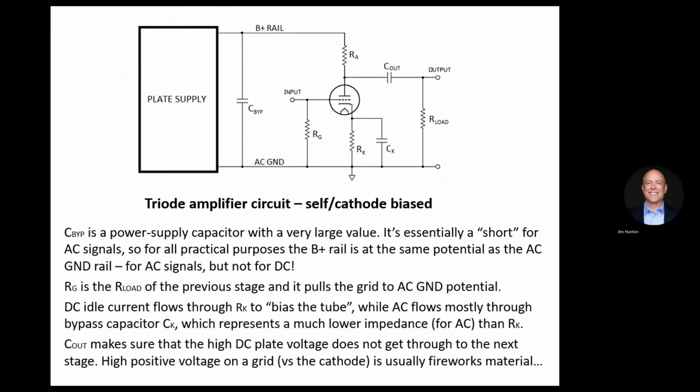Why? Because from here to there, the current flows downward. There's a positive voltage here. Let's say if it's 2 volt positive, the cathode is at 2 volts. This is at 0 volts. Well, guess what? It's in the negative 2 volts versus the cathode, the grid. Okay, so there's no fixed voltage. Okay, everything is relative, and voltage is potential, one potential versus another. So as long as we have a cathode at a higher voltage, positive voltage than the grid, we're in a negative grid voltage. We're on the curve, okay, at a bias of -2 volts.